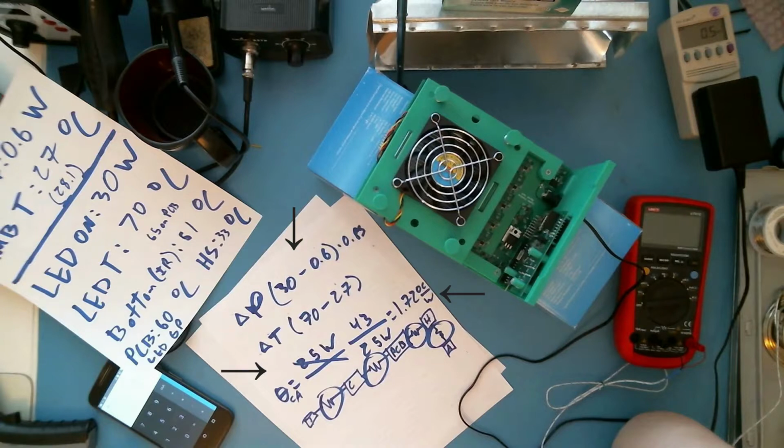In a previous video, we estimated that the junction to ambient thermal resistance would be about 6 degrees C per watt. This was assuming a number of thermal vias, thickness of the board, etc. Doesn't that sound great? Well, kind of, except for the fact that we didn't account for any thermal resistance of the heatsink. And then we got a total number of 1.7 degrees C per watt based off of our measured data. What happened? Well, I think we forgot to account for some things.